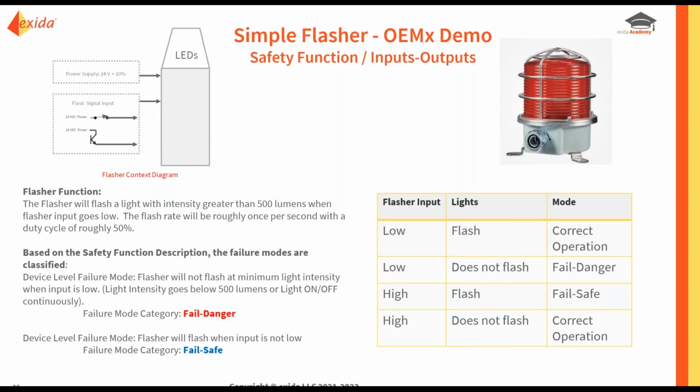Now, based on that safety function description, it's pretty clear what the failure modes are. If the input goes low and this device does not flash, that's fail danger. If this thing starts flashing when the input didn't go low, that's fail safe.